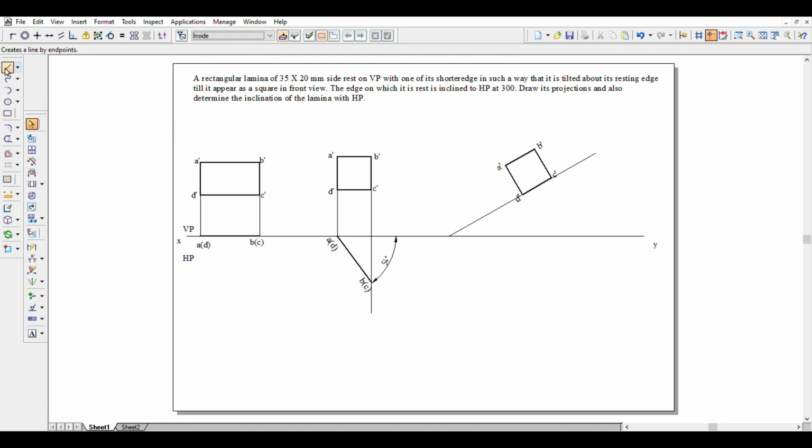question. Now we'll use the line tool to draw the extension lines. We have one extension line from A. Keep the line tool active. From B, we will extend another line until we get the point B intersecting with B. So we'll just extend the line at 90 degree. We can extend a line from C also.